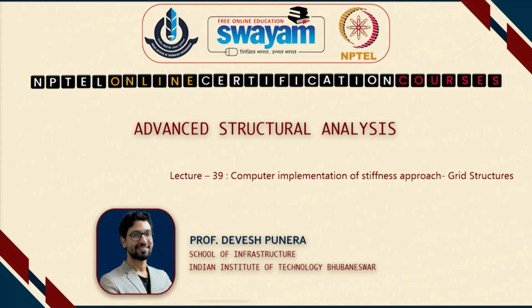We have discussed the basic concepts of the plane frame in the last session. We implemented it in a manner such that the computer code related to the similar process can be prepared, and then we also looked at one problem which was solved using the standard stiffness approach, which is suitable for computer implementation, in the last session.